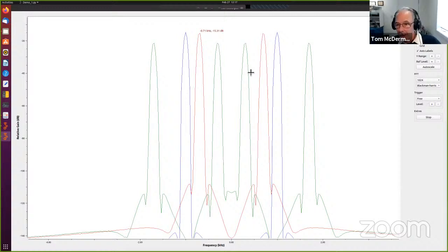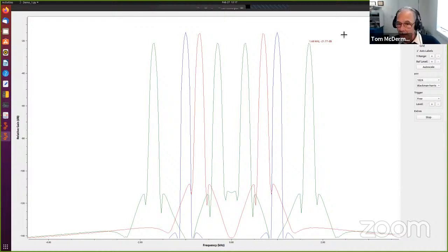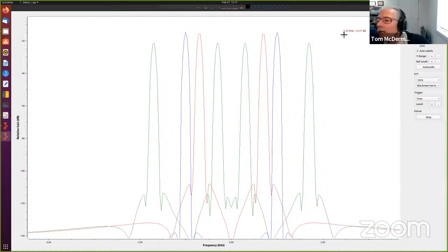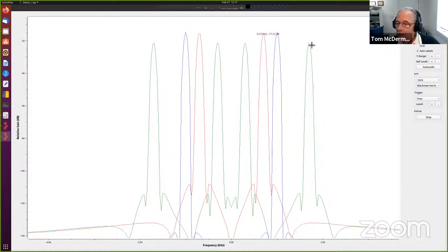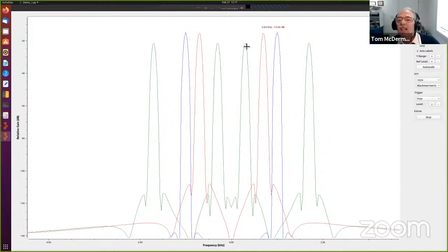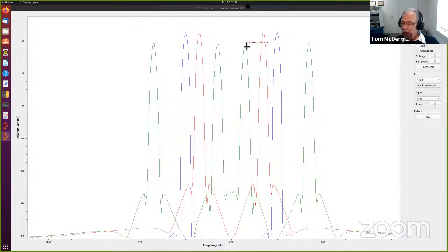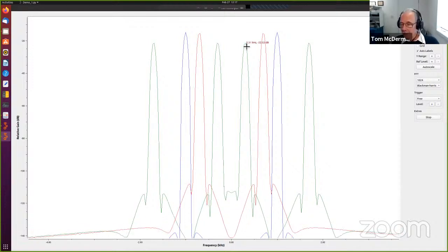And then the green pips are the product of multiplying this carrier by that carrier. And what you see are the sum and the difference components. So the sum here is at 1700 hertz, 1000 plus 700. And the difference here is at 300 hertz, which is the difference between those two carriers. So here we can see that a real multiplier produces sum and difference components.